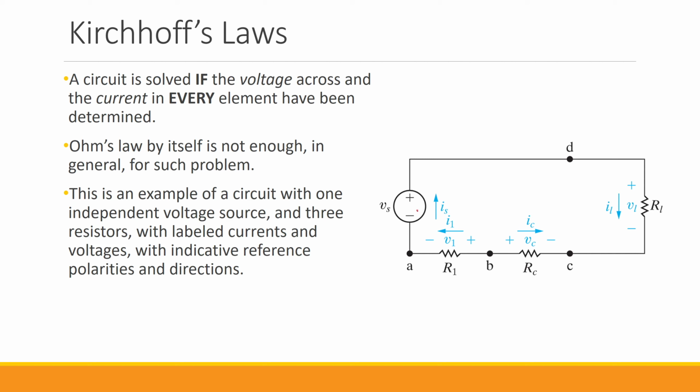For the voltage source, since our understanding is that it is providing power, I put the reference direction for the current in the reverse direction of the voltage drop, or in the direction of the voltage increase. But we will get to more details later on. So this is based on the assignments that we had for the voltage polarities and current directions.